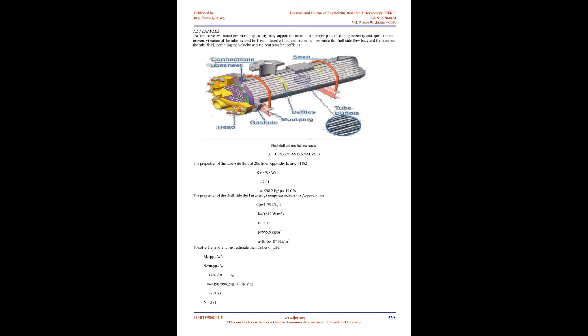By means of this model, an efficient and versatile method of predicting transient response of multi-pass shell and tube heat exchangers is developed. The method allows for the effect of maldistribution on transient process, influence of heat capacities of fluids and solid components, arbitrary inlet temperature variations and step disturbances of flow rates. General forms of initial conditions and 2 different flow arrangements are considered. A general form of the solution for steady state and dynamic simulation is derived. Temperature profiles are determined with numerical inversion of the Laplace transform. Some examples are calculated and the effect of maldistribution is discussed.